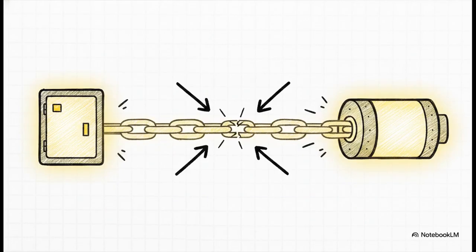Let's look at the real-world consequences of this. You could literally spend a fortune buying the most incredible, top-of-the-line variable speed drive and an absolute beast of a drilling motor. But if you have an undersized transformer upstream, or even just a poorly rated feeder breaker sitting back in the switchboard, you've created a massive bottleneck. That single weak point will completely throttle your drawworks performance, and all that expensive downstream hardware is totally wasted. The whole path has to be sized together, period.